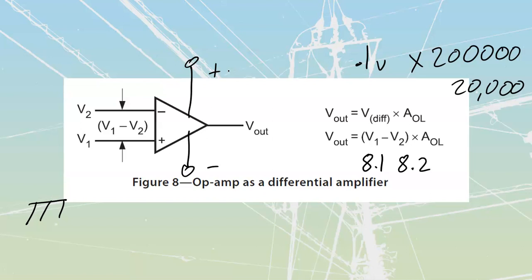If the voltage is different, then my larger one is going to drive my current through the smaller one. And so what we'll do is use the differential amplifier to either apply more power to the one that needs to have it, or sound an alarm, disconnect them from the circuit, etc. There's all sorts of stuff I can do with that signal, but all I'm going to be looking for is what that signal actually is going to be.